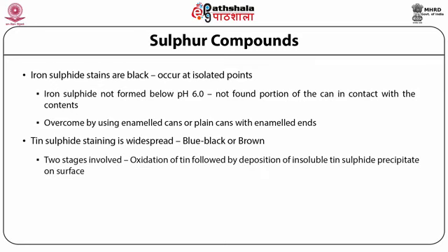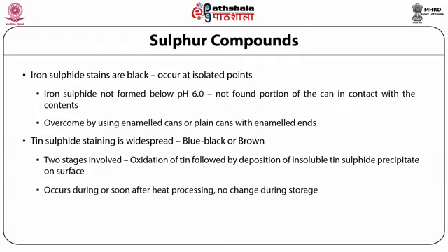Two stages are believed to be involved: an oxidation of the tin, followed by deposition of an insoluble tin sulfide precipitate on the surface. This occurs during or soon after heat processing and shows little or no increase in intensity during storage.